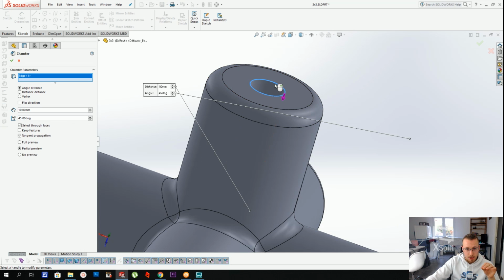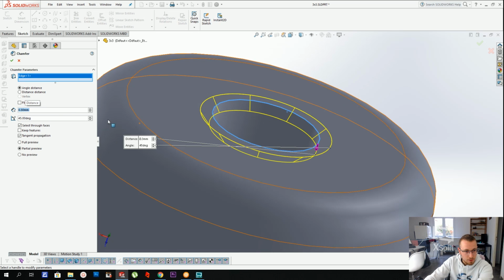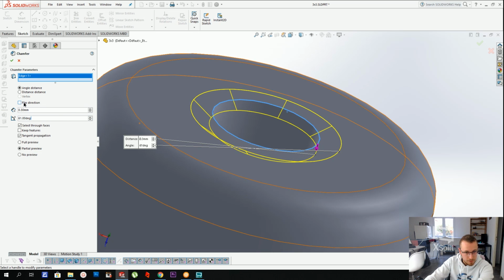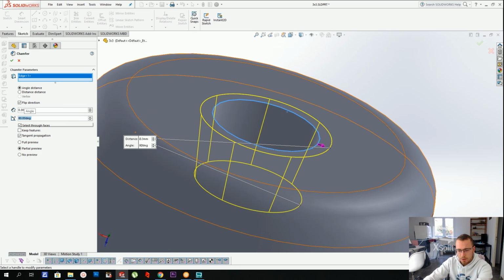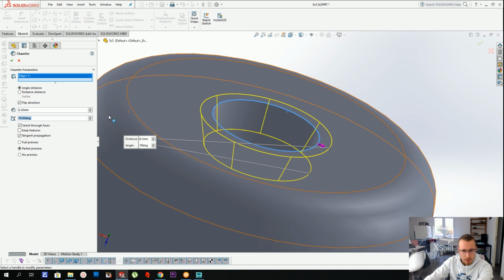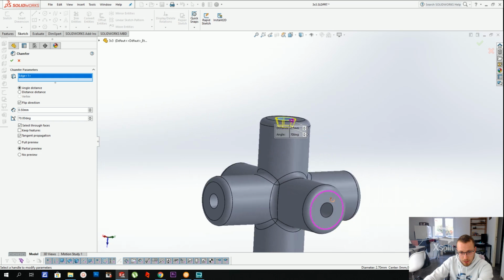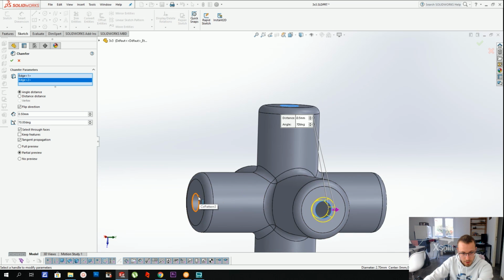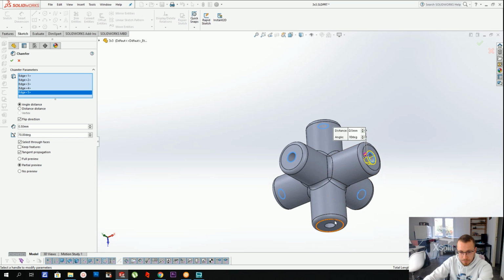And here you put a chamfer there, right there. That's 0.3 millimeters, and well, let's flip the direction. Make it 60 degrees or something. It's really optional. I'm gonna make it 70 degrees. And yeah, that's 0.5. 70 degrees and 0.5. It's completely optional, but I'm gonna explain why it makes this whole screwing process easier.